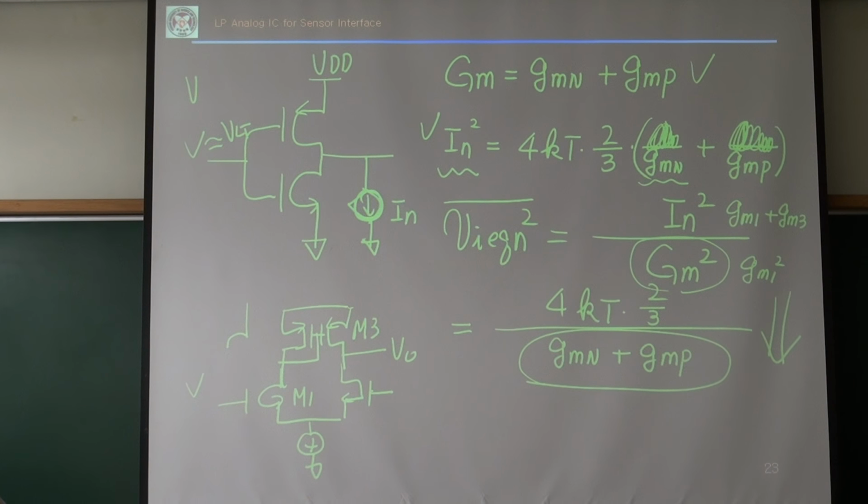At half VDD, this operating point, this one may be in weak inversion or some lower. So you said a small VGS minus VTH increases the voltage gain, but this one has a large VGS minus VTH.